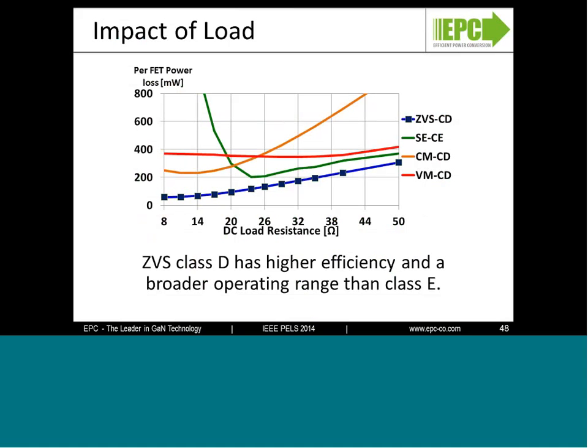When you look at the zero voltage switching class D, it uses, again, a very traditional current source to achieve the zero voltage switching during the dead time, and that makes this topology very load insensitive and can give you good performance over a wide range of loads.